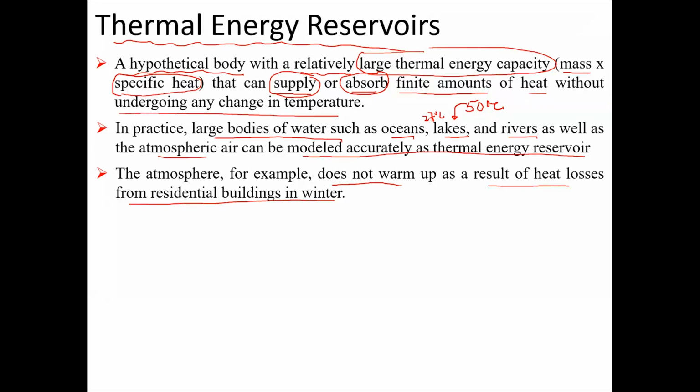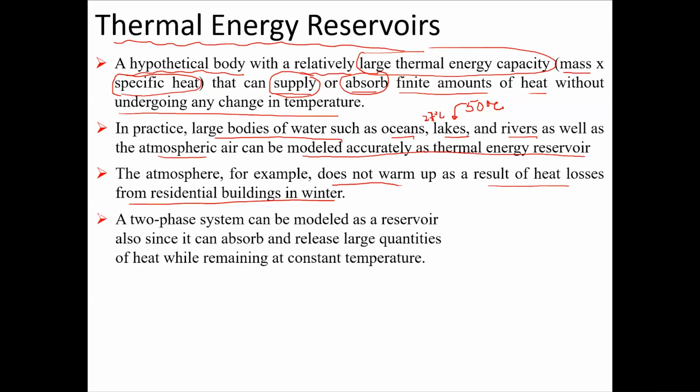Let's say you have liquid and vapor in equilibrium together. Can you consider that liquid vapor mixture as a thermal energy reservoir? Yes, sir. Why? Because this two-phase system can absorb and release large quantities of heat while remaining at constant temperature, unless and until the phase change takes place.